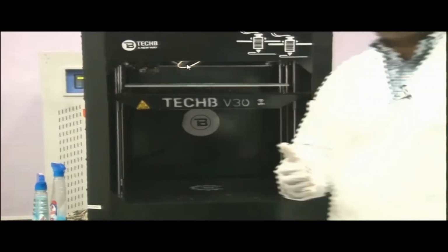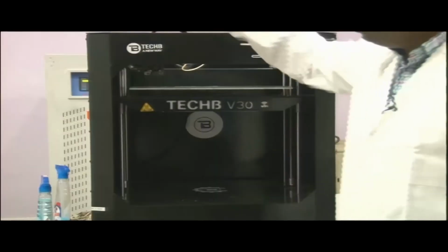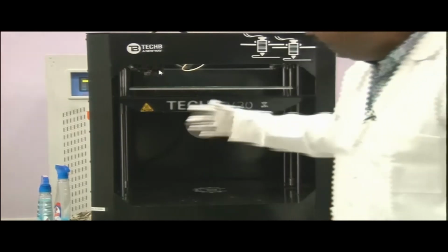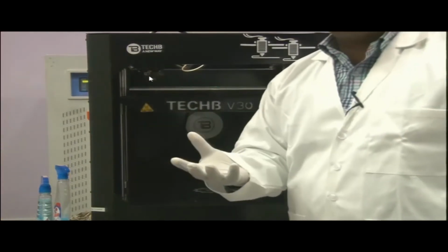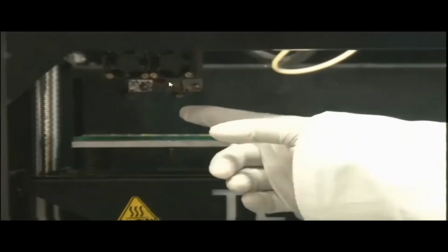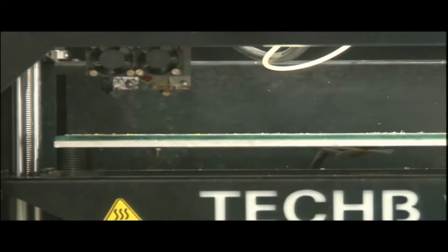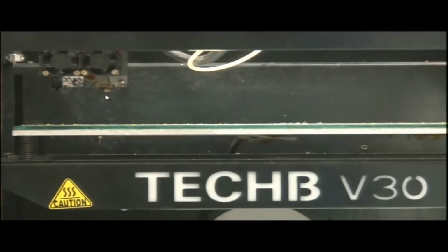So it is coming through this tube. We will show this demonstration. Now this portion is known as the head, where the nozzles are attached. So the material is fused and comes out from these nozzles. There are two nozzles here, nozzle A and nozzle B. Why are two nozzles there? We will explain. One nozzle is for the base material, another is for support. This is a very fine orifice; the orifice diameter of the nozzle is 0.4 mm.